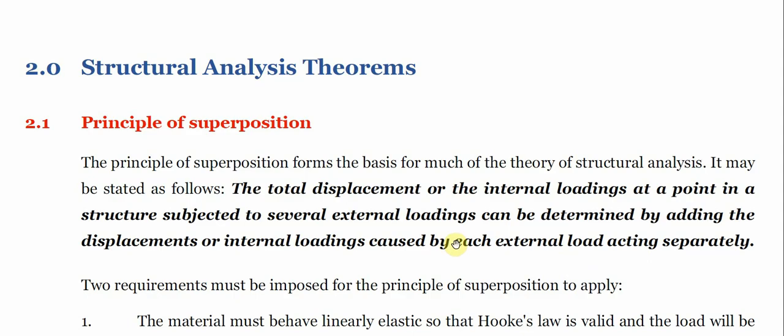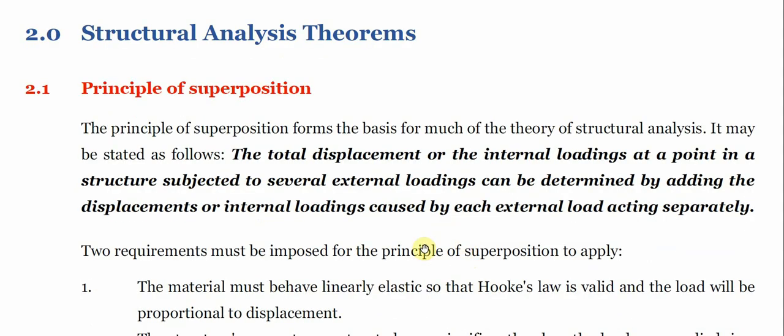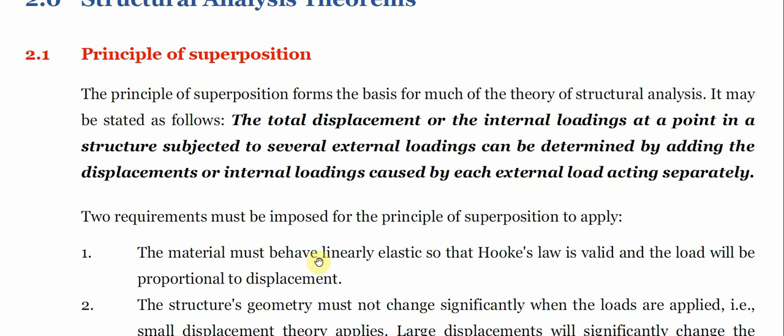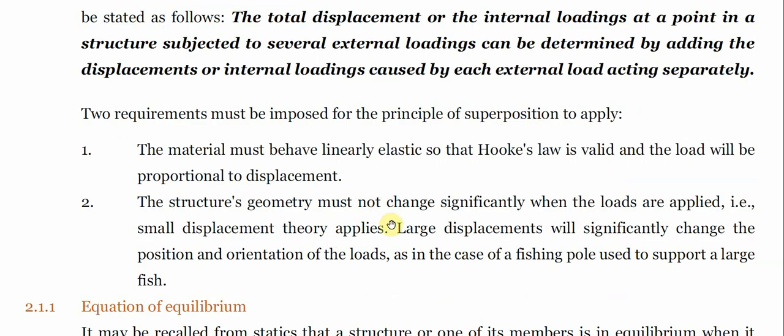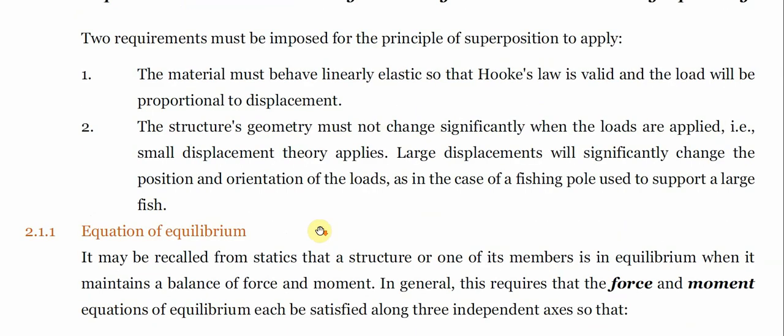So there are requirements that must be followed when using the principle of superposition. First is that the material must behave linearly, that is, it must obey Hooke's law. And secondly, the structural geometry must not change significantly, that is, only small displacement should appear, not that it will deflect and maybe distort out of shape.